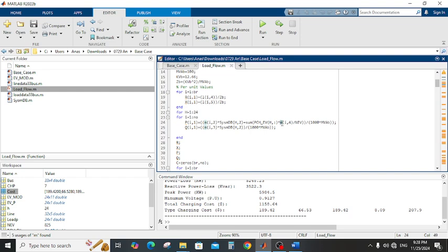This is the number of EV at each bus divided by the total number of EV, multiplied by the EV power charging profile for each type, and after that we sum it over the whole types. What does that mean? It means in each bus we have 10 different profiles, so dependent on the number of EVs.